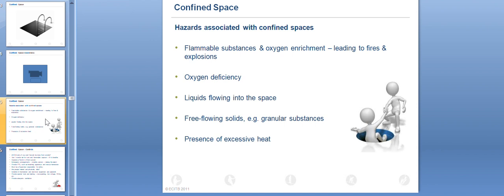Oxygen is mandatory for our breathing. In a confined space, the oxygen level we have to maintain is more than 19.5% and less than 22.9%.